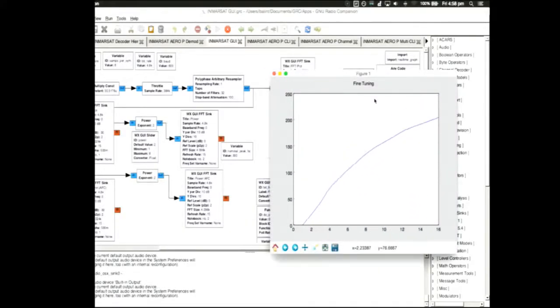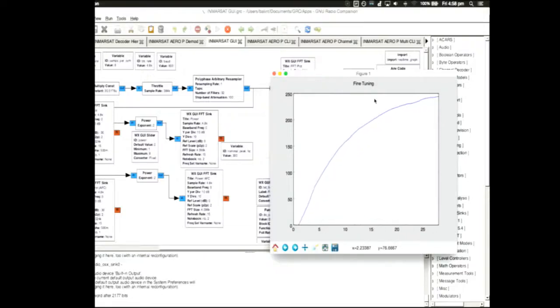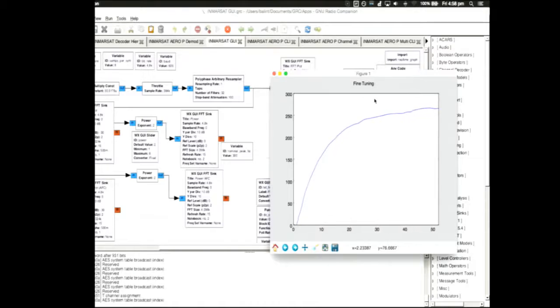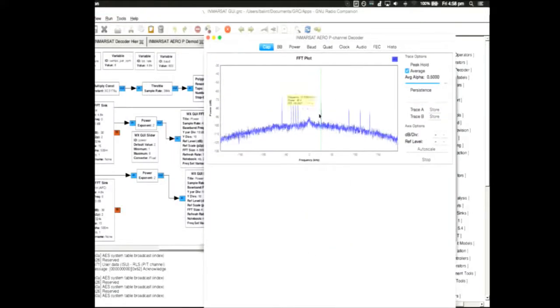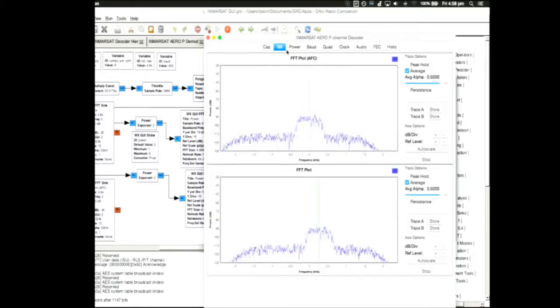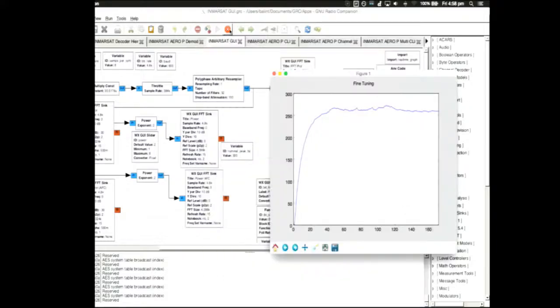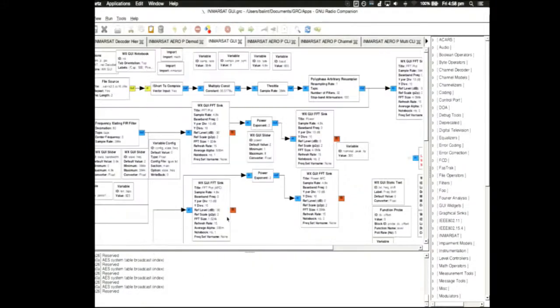So this is showing you, as the program's running, that the receiver is adjusting its fine-tuning of the incoming signal and moving the baseband, and now it's actually locked on the signal properly. So that's about a 250-and-a-bit-ish hertz offset from where we clicked on this to where it actually needs to be centered up. So that's this offset that's showing you in that graph. So how does that actually work? Well, it's really quite simple. So let's have a look over here.